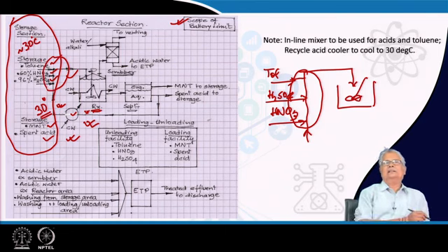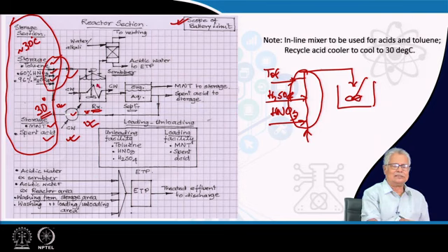Now, the reaction here is between liquid phases. There is no catalyst present. It is well mixed because of the presence of the stirrer that you have in your CSTR. The heat is being removed possibly through some heat transfer surface, the other side of which you will have a cooling water to remove the heat.